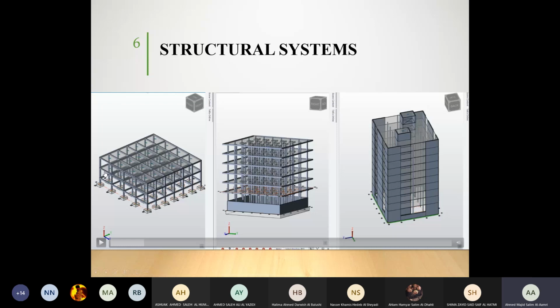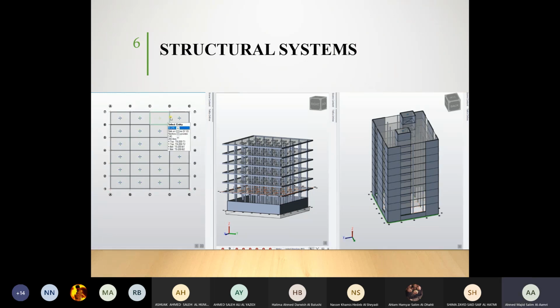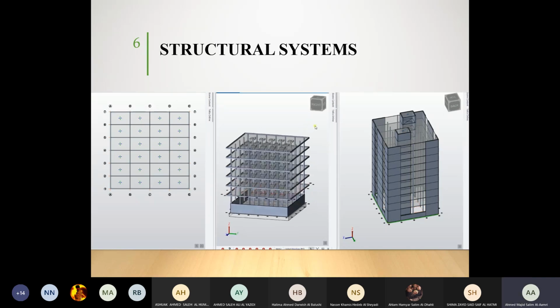You can see it's columns, beams, slabs only, whatever we refer to as a solid slab system. And this is good for 3 stories and lesser. Okay. So you can see in this framing, you are seeing your slabs, beams, and columns. Okay. Now the other system,